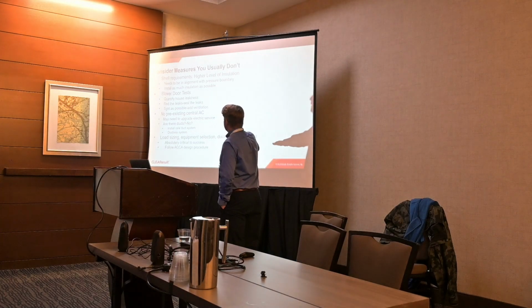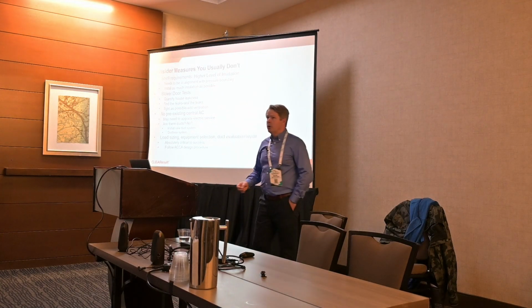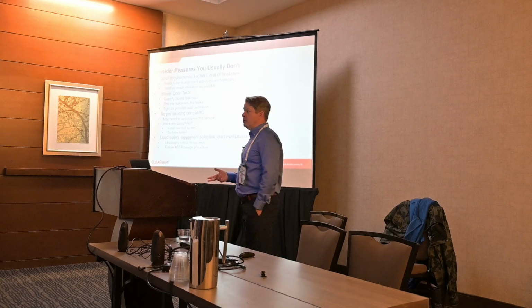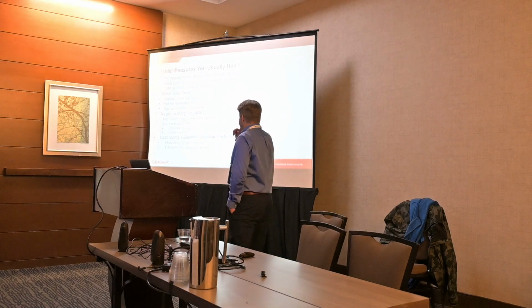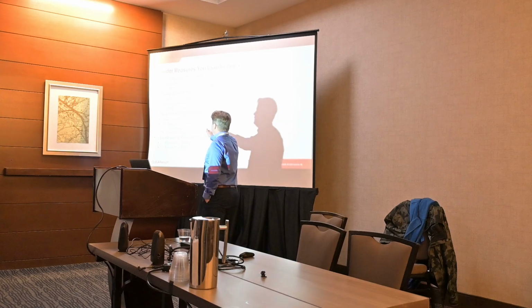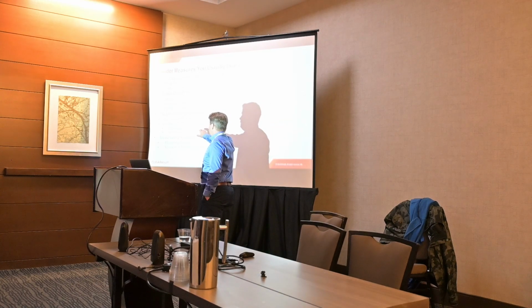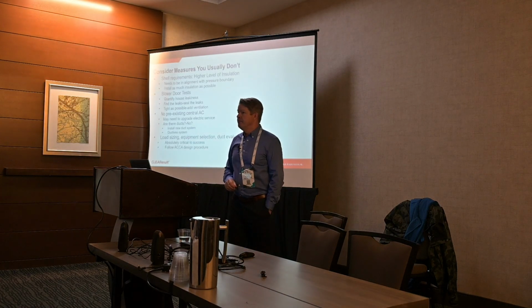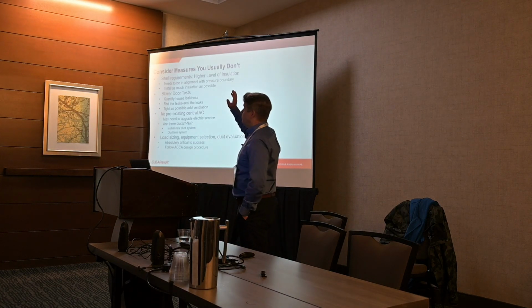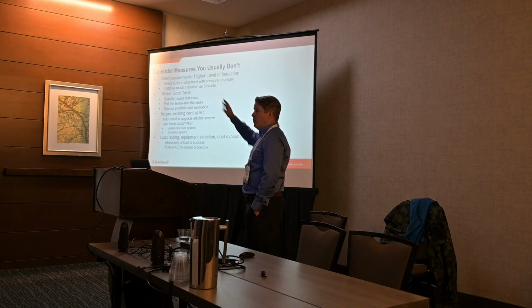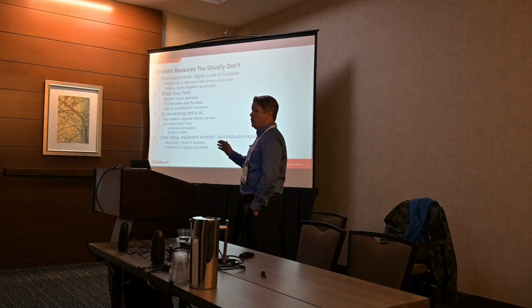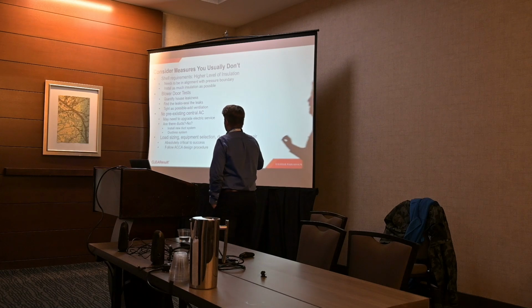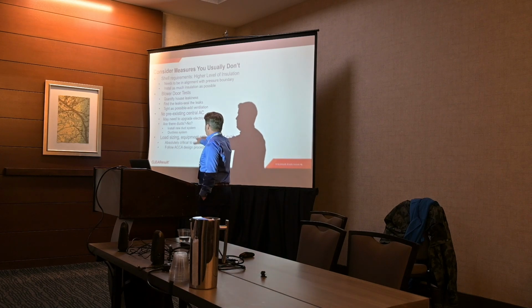The duct system, is there a duct system? If there isn't, we're going to need to install one or do ductless mini splits. Ducted systems, when they're done correctly, will probably deliver better comfort than ductless systems, okay? Because the ductless system is distributing from one place in a big room or a good-sized room. Distributing the heating and cooling from one place can give you entrainment problems and mixing problems, right? So when you can have a really good duct system that does what it's supposed to, that's better than a ductless system.